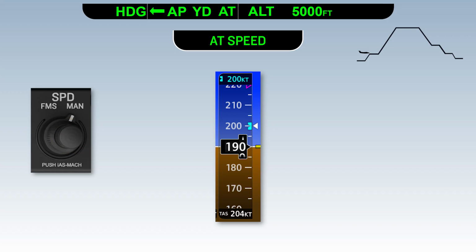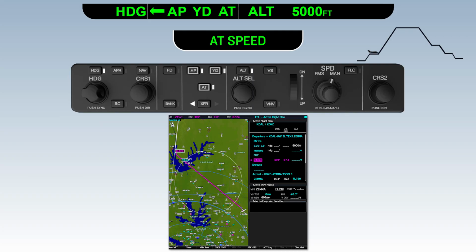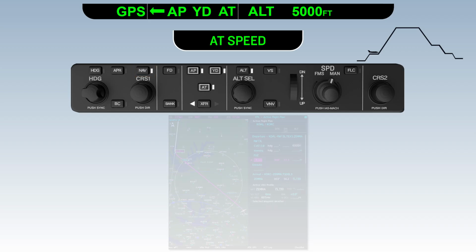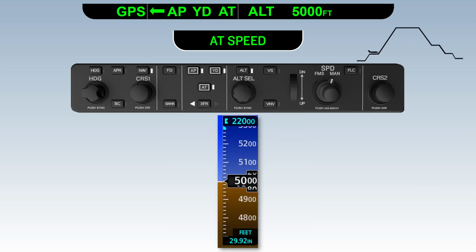the selected airspeed. Now ATC calls and tells us to proceed direct to Bleco, climb and maintain flight level 220. We'll handle the lateral navigation first by setting direct to Bleco and pressing NAV. For the climb, we'll raise the altitude bug to flight level 220 and press FLC for the climb. The autothrottle will transition to AT climb and move the power levers forward to maximum climb power.